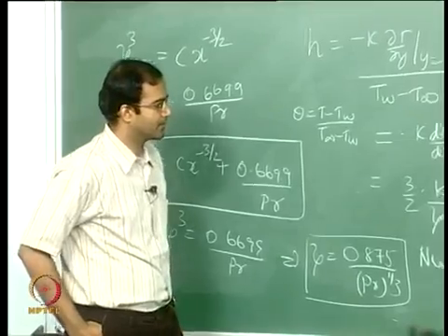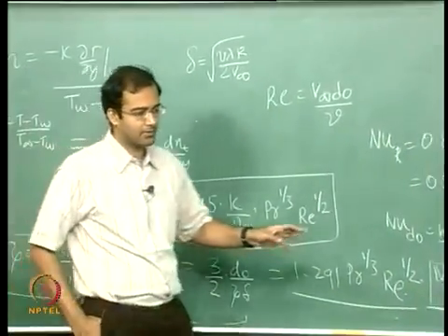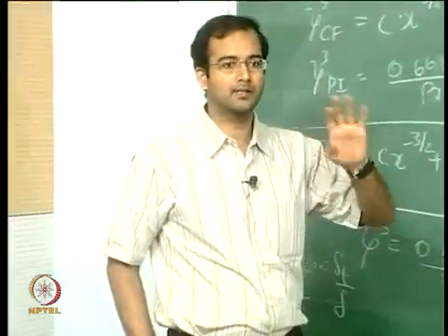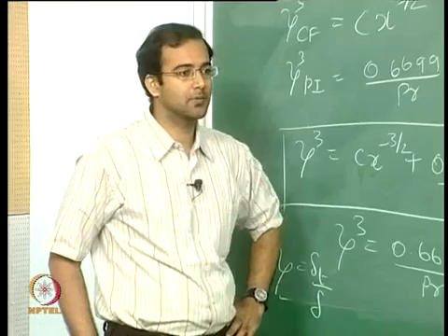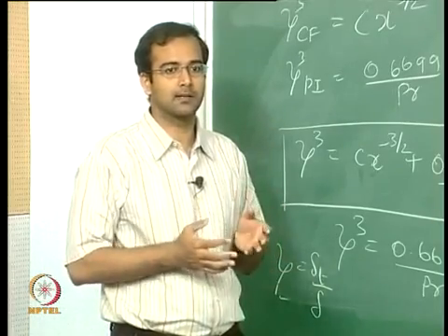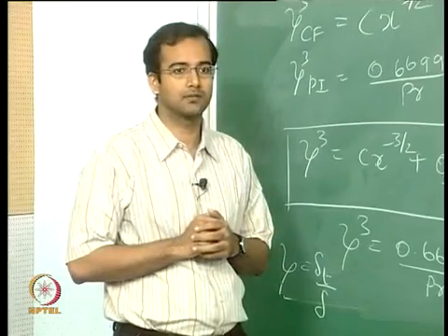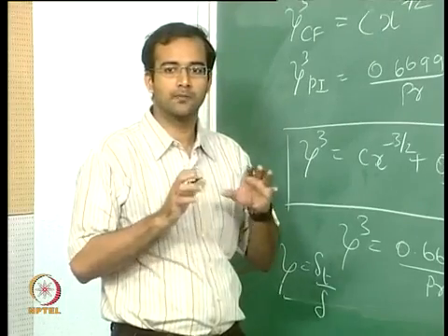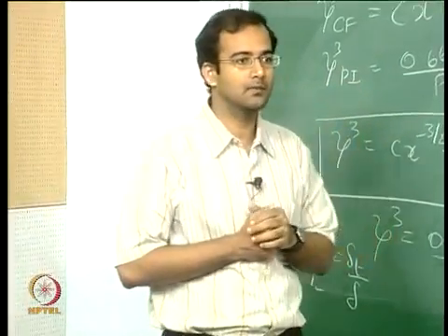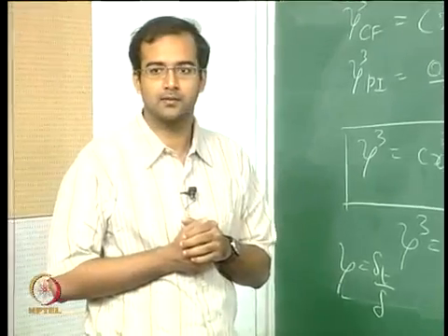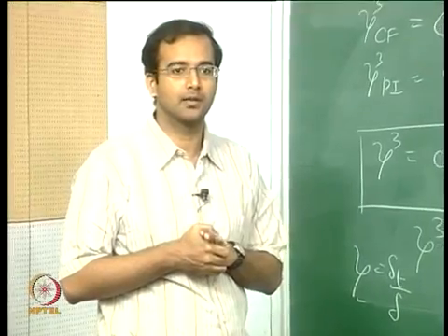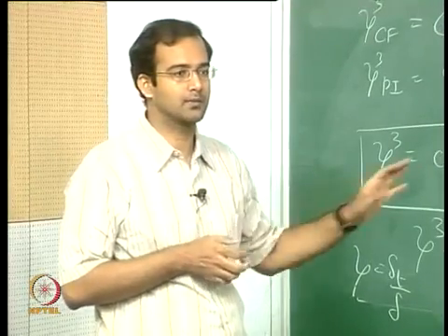Okay, so these approximate solutions are therefore very useful. You don't have to solve the ODE numerically, okay. So only guess some profile and substitute, and finally you find the resulting expressions, correlations for Nusselt number, especially the integral quantities like Nusselt number are pretty much similar to the similarity solution, okay, although the profiles themselves may be different. For example, if you assume a linear temperature profile, it is completely off from the actual temperature profile, okay, but the integral quantities like skin friction coefficient and the Nusselt number, you get a reasonably good agreement with the approximate solution, okay.